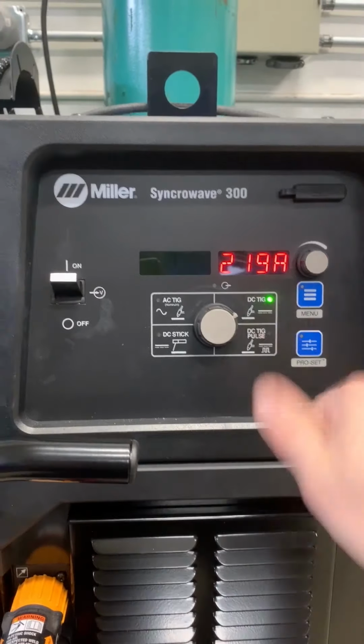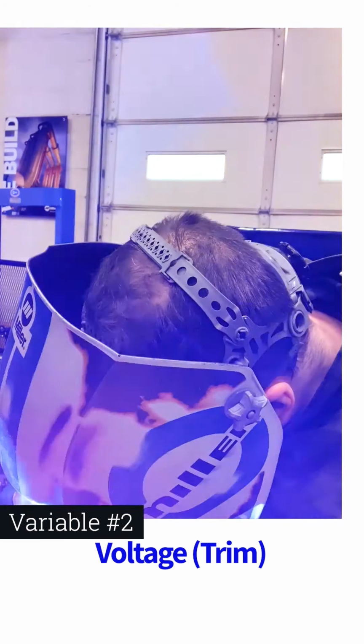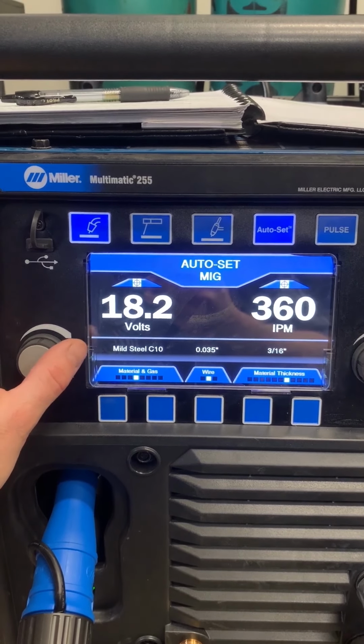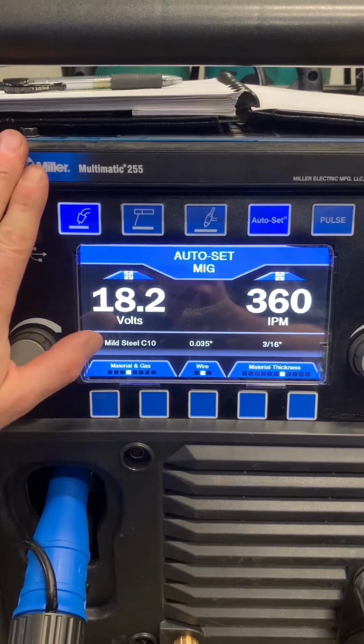But that's how I adjust amperage up or down on the front of these machines. And up next, we have voltage and trim. To adjust voltage up or down, I'm going to use the left dial on the Multimatic 255. And this is going to help me determine the height of my arc that I want to have. This is a big driver on my overall heat input. It controls the amount of bead appearance that I have. It controls the spatter levels that I have in this process.